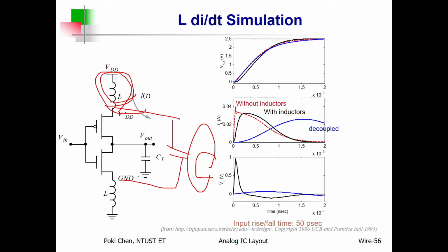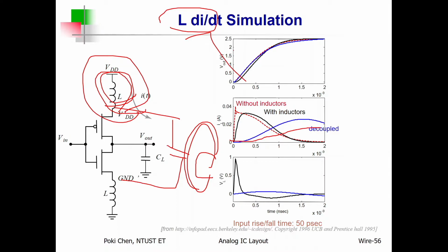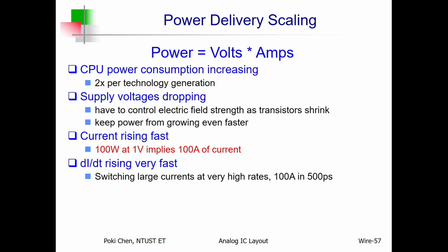It means the capacitor can help you absorb the voltage drop very much during such L di/dt impact, right? That's it. You can see with the coupling capacitor, not only the current variation, but also the voltage variation can be reduced very much. But you need to pay the price. What kind of price? A large enough decoupling capacitor. Got it? Let's go further.